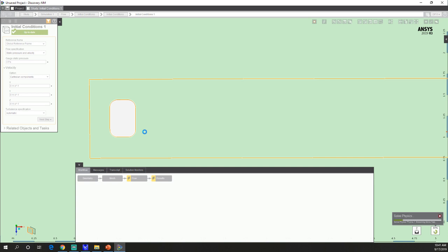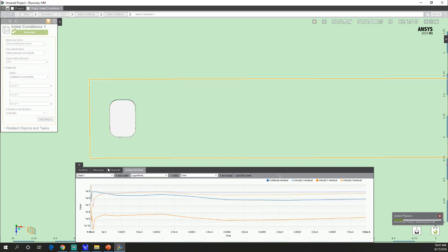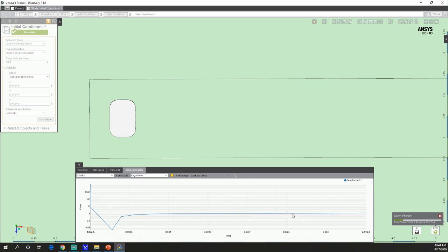The nice thing about AIM is that, as you saw, we don't have to specify the time step. AIM uses a different time stepping calculation, so it does a first order and second order time stepping and sees what the difference is, and that allows it to adjust the time step to try to capture things that are happening in the flow automatically. So this makes it much simpler to run transient simulations. And you can see it's going here, and it's calculating our drag on the cylinder.